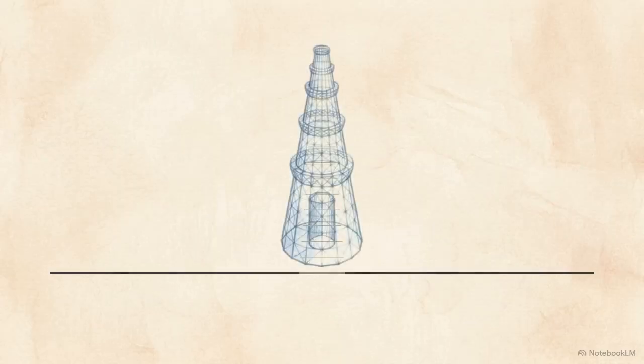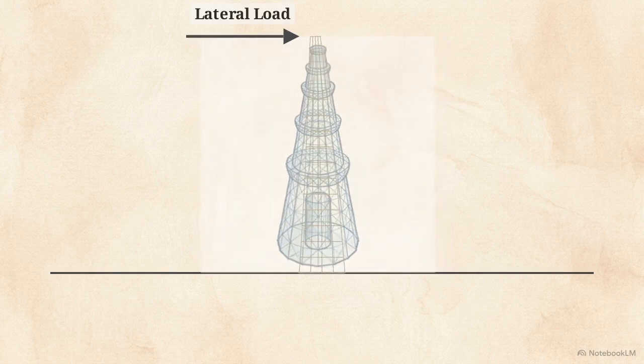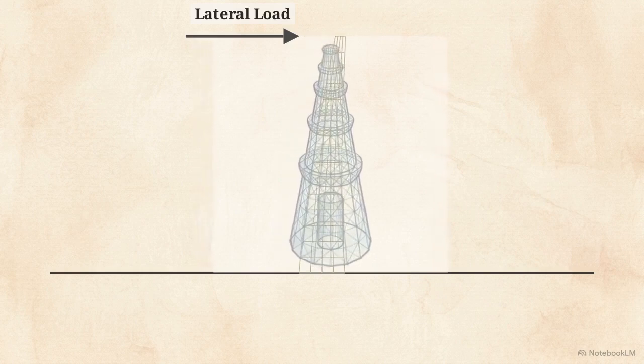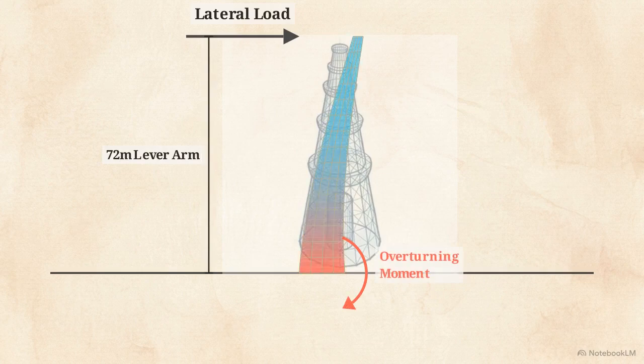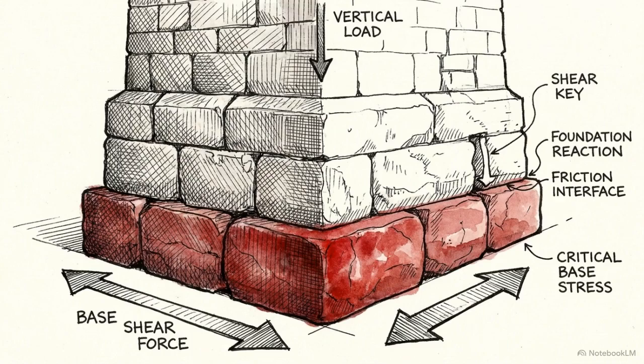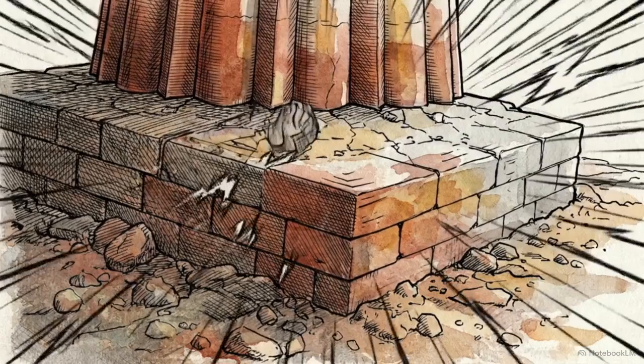The static test applies lateral forces based on the structure's fundamental mode of vibration, the simple primary side-to-side sway of the entire tower. In this single bending arc, the 72-meter height acts as a lever, creating a massive overturning moment localized at the foundation. Because this model ignores high-frequency dynamic forces, the mathematical outcome defaults to base shear. This creates a static illusion, where the highest stress appears at the foundation, obscuring the structural realities of the tapered upper levels. A real earthquake doesn't push slowly.